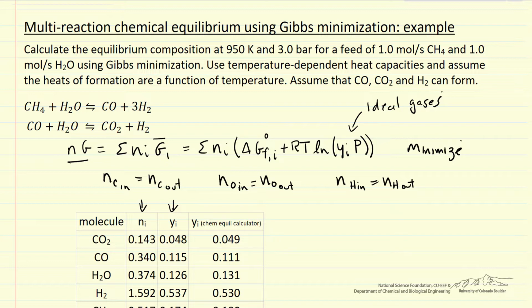And then, just as a check on the spreadsheet, I compared to an online calculator, and the reference to this is given in the spreadsheet, to see if we're getting pretty similar values. Indeed, they differ at most about 3% or so. And that difference is exactly which heat capacity term we use to try and represent the heat capacity over this temperature range. It's going to give us slightly different answers. And so this confirms that indeed spreadsheet's doing what we think it's doing.